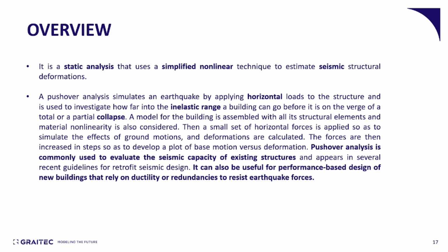Then a small set of horizontal forces is applied so as to simulate the effects of ground motions, and deformations are calculated. The forces are then increased in steps so as to develop a plot of base motion versus deformation. The pushover analysis is commonly used to evaluate the seismic capacity of existing structures, or it is also used for the performance-based design of new buildings in order to rely on ductility when designing for seismic forces.